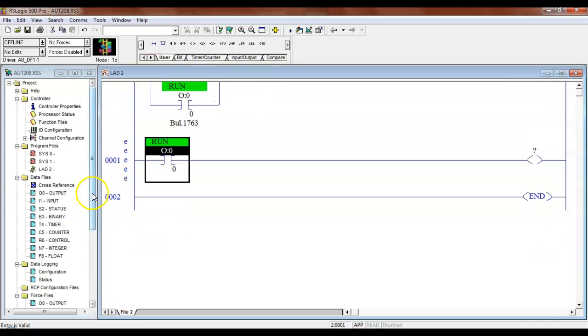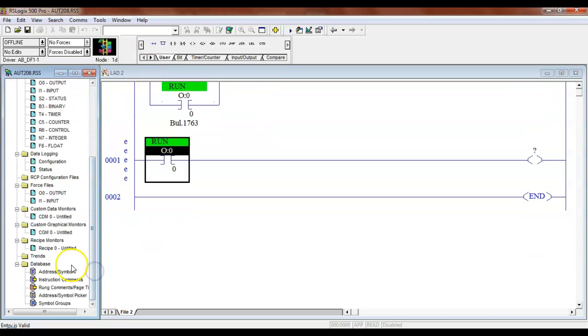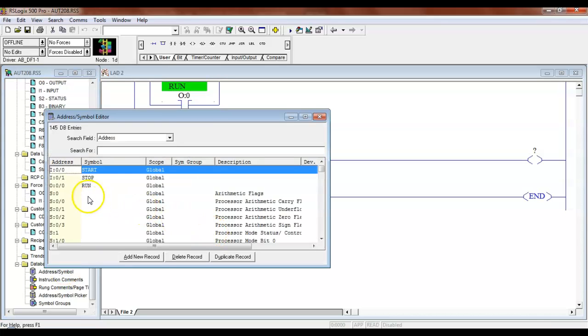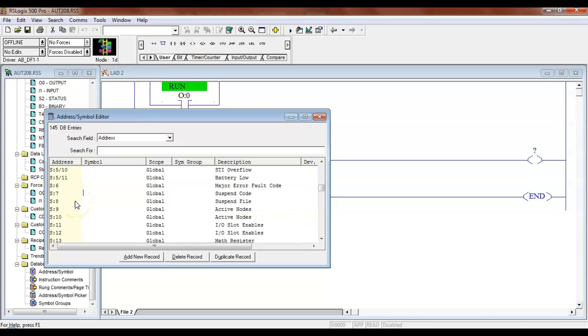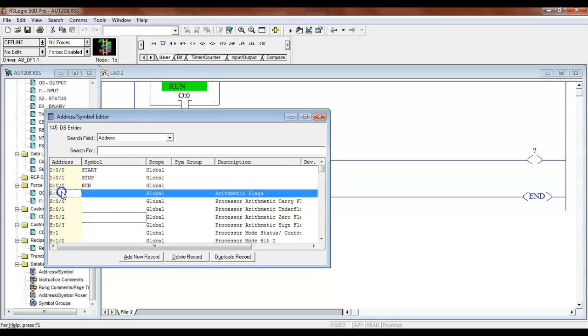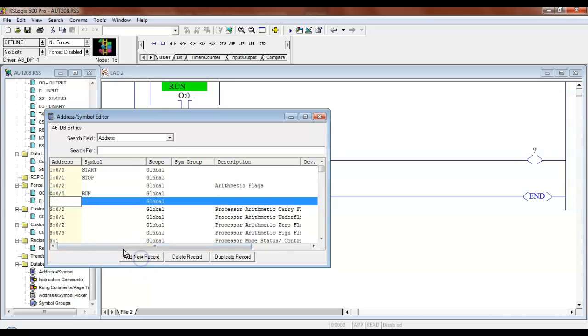So what we can do before we even start is come over here into this tag, this symbols table, and I can go ahead and assign an input. So I could assign input 0/2, then give it a name. No, it didn't work, guys. Oh, I'm sorry, add a record. And then we're going to add an input, :0/0. Not 0, which one hadn't I used? Let's say 4/4.